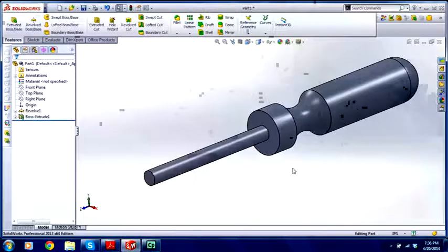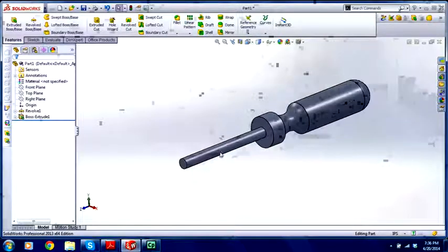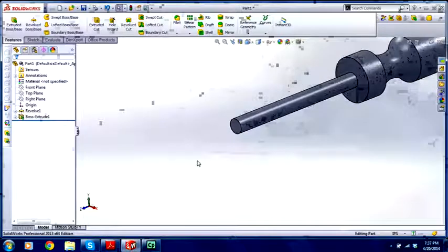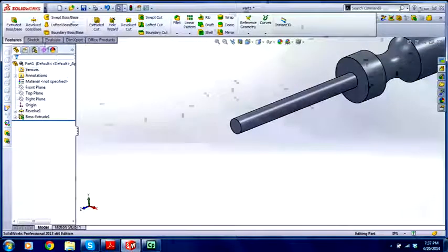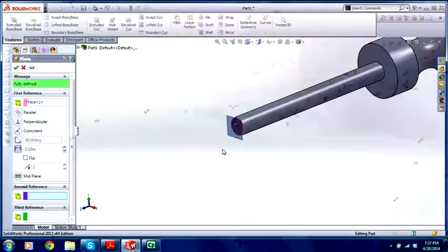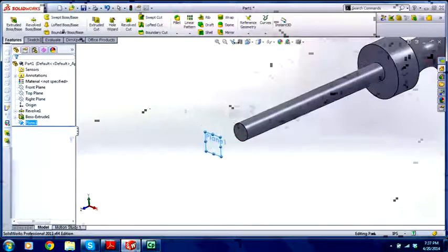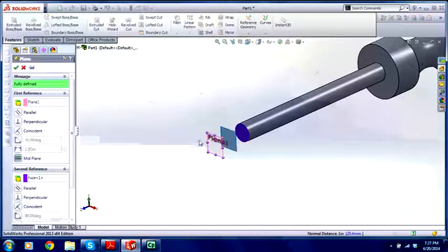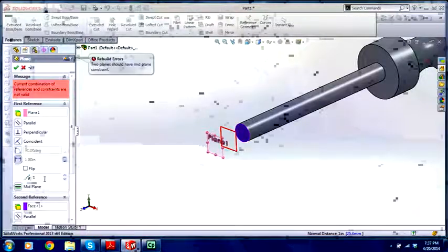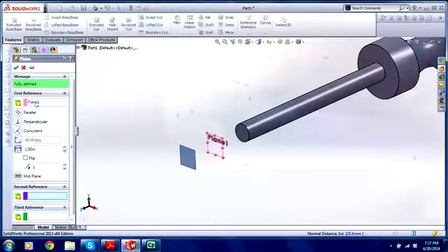Okay, first feature, revolve. Second feature, extrude. The third feature is going to be the loft. So let's get 1 inch away from there. There's going to be a profile, a sketch. So let's get a plane. I'll click this face and I'll go 1 inch. Right. I'll get another plane from there. I'm going to make it 2 inches. Now, just one reference is all you need, and there's going to be an offset of 2 inches.